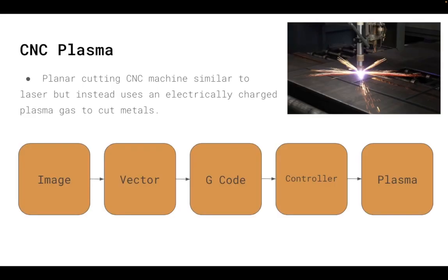I am a CNC plasma cutting instructor, and so this is what we're going to be focusing on for the application of graphs with digital fabrication. Here I have a typical workflow of any kind of plasma cutting project. So in general, you're going to come up with an idea, which could be a drawing, something digital or something physical. And then you're going to take that idea and convert it to a digitized vector file. Vector files are different from raster files in that the lines are calculated using formulas and they can be infinitely scaled or minimized, where rasters are just pixel point representations of something.